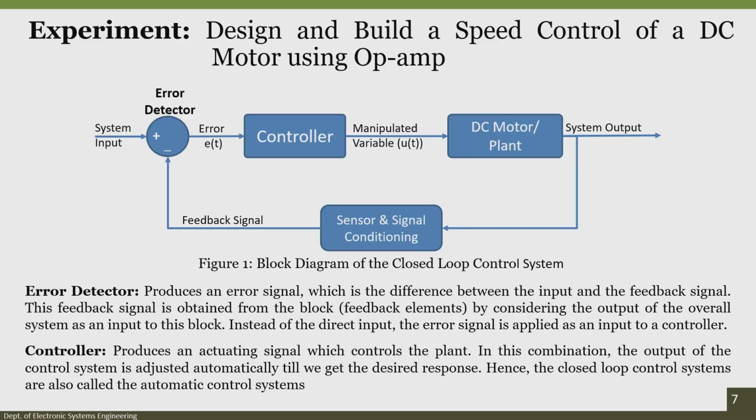Since we are using a data acquisition device which can support counting pulses as well as digital pulses, and can also acquire analog input, we can acquire the signal in a digital way, a counter way, or an analog signal way.